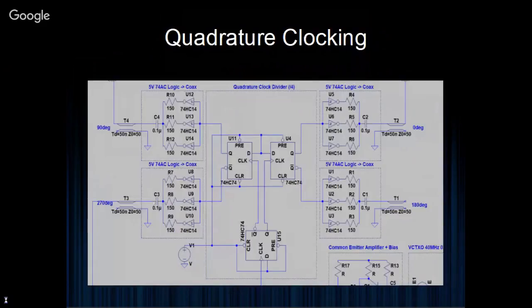So we have one clock here driving these two clock transitions. One is inverted, one is regular. And the thing to note with a D flip-flop when it's driven by the clock and latching the data in on each positive clock transition, sorry, I made a mistake there. That's pretty bad, but at least I got it on this occasion. So the complement of the status of the D flip-flop is meant to be fed back into the input, such that on each clock transition you have a toggle. That's what I stuffed up, so never mind, I'll have to fix that up.